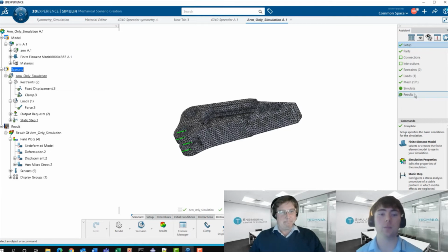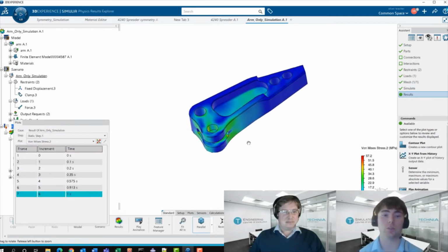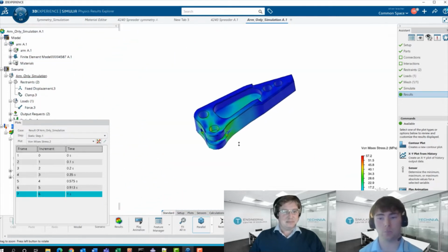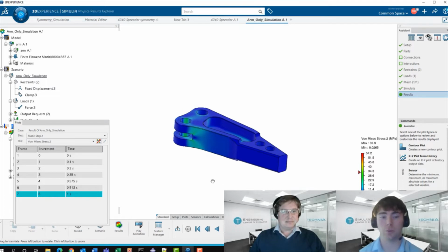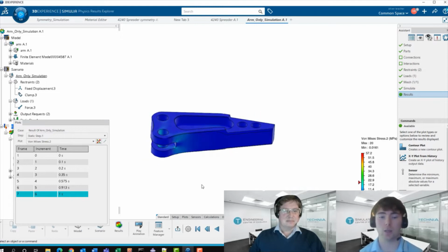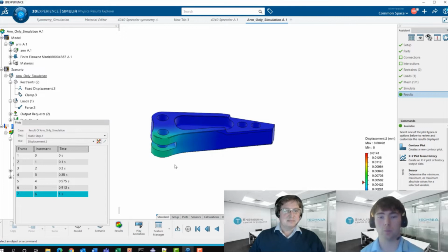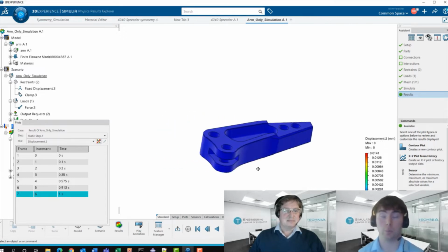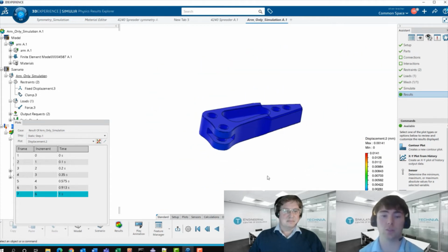Yeah, absolutely. We could apply those forces to the places we just mentioned, and then we could fix the top of the arm to enforce the bending. That would give us the worst case scenario and allow us to observe the part's stiffness and how it would deform. I'd also remove the black polymer tips, as they won't impart any significant stiffness on the model, and all they're doing is just increasing the complexity in this case.